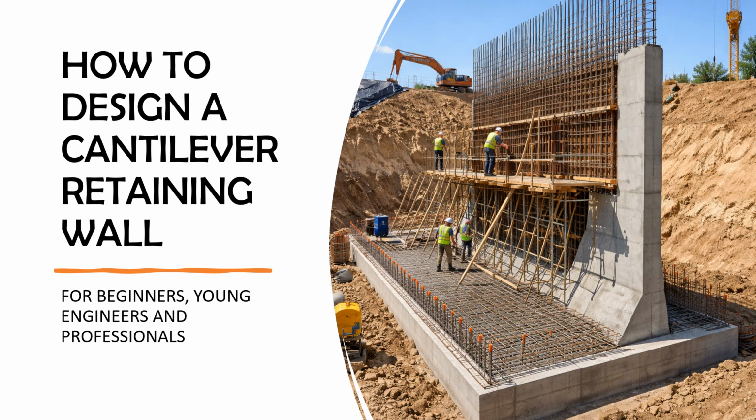This is the structure of a retaining wall. A cantilever retaining wall has a stem, it has a base slab where the front of the wall is the toe, the back of the wall is the heel, and so you design it against overturning, against sliding, and against soil bearing pressure. You ensure that the bearing pressure is adequate enough to carry the retaining wall, while the retaining wall is meant to retain earth between two different surfaces or two different levels, right?